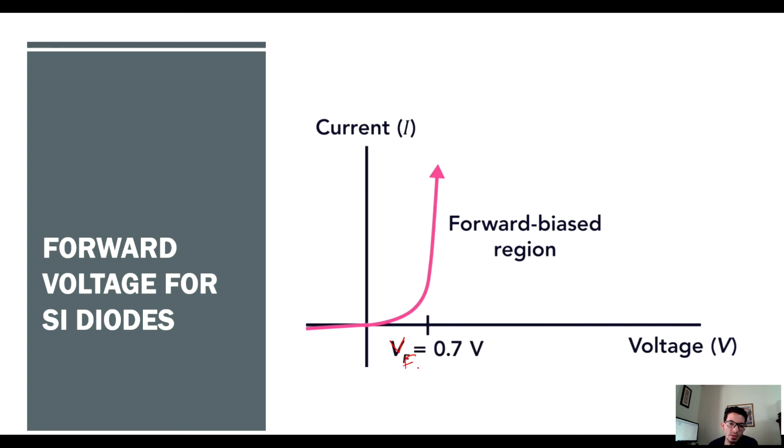When you buy a diode, the specification page will bring something called VF, which is the forward voltage, which means that there's a minimum of 0.7 volts needed to let current go through. And as we mentioned before, the current will increase exponentially after a very small increase in voltage. But you have to meet the requirement of the VF voltage to let any current go through the diode.